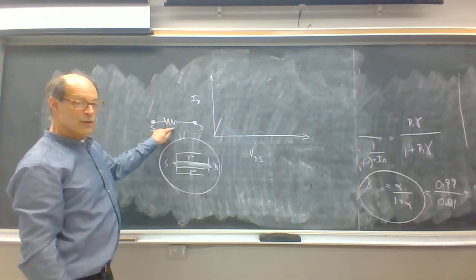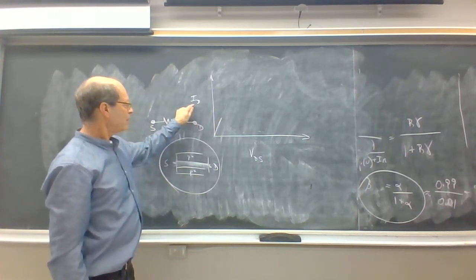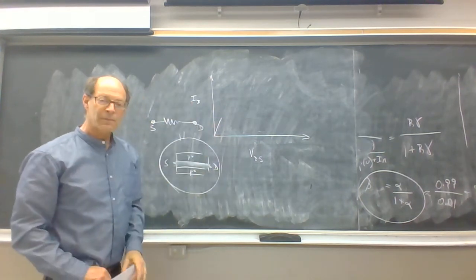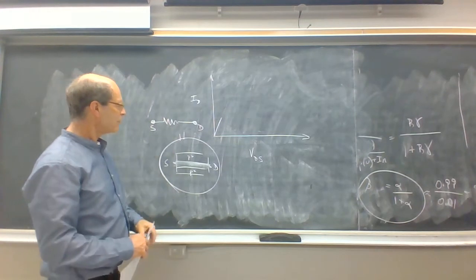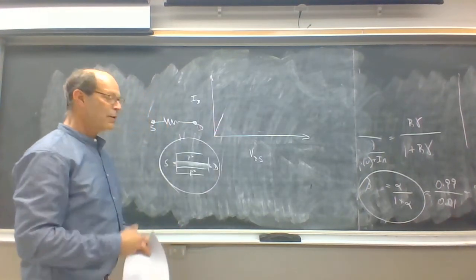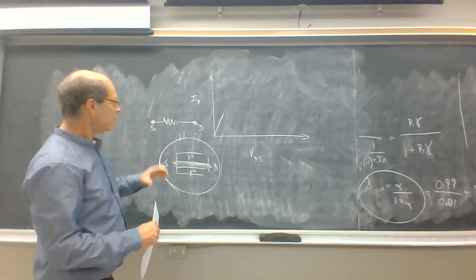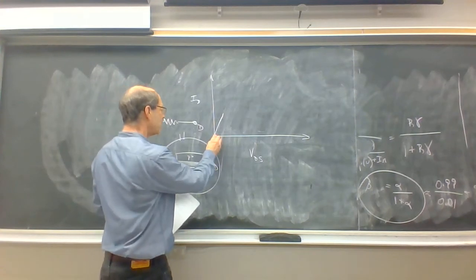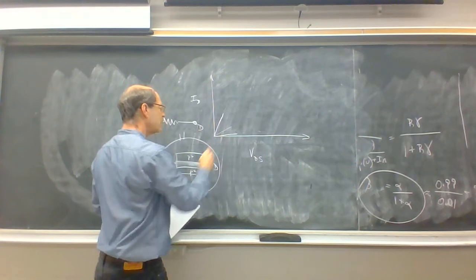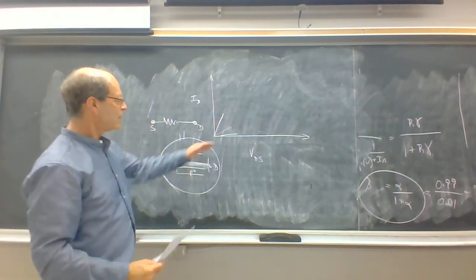If you model this as a resistor, then we should get a straight line relationship between the current and the voltage through that channel. And if you were to increase the gate voltage, the depletion widths would get wider and the resistance would get higher, and you'd get a reduced slope.